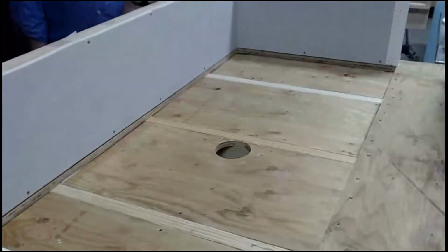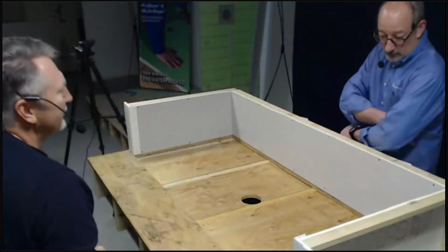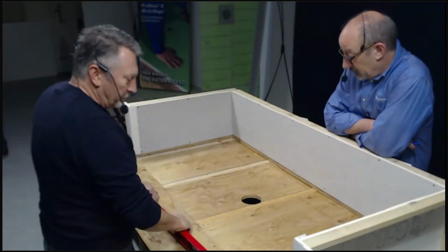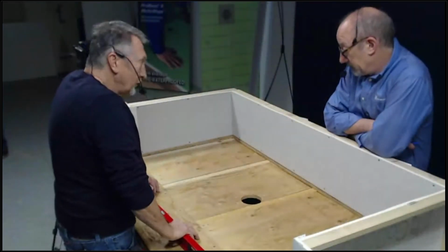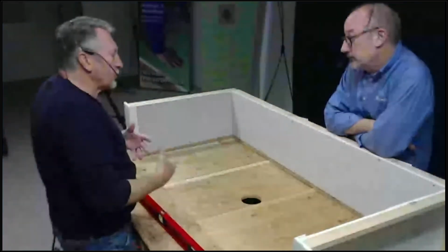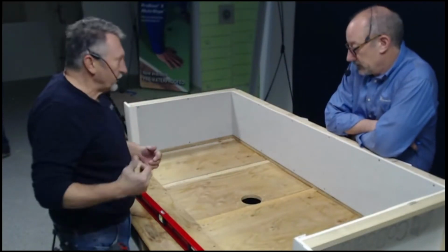Find the only knot in the 2x4. Found the only knot. Okay. So we've now basically just lowered this thing essentially 3/4 of an inch. We're flush with the top of the joist here. So you always want to confirm again that you are flat and level with this. If you are, then it's ready to go for the base.